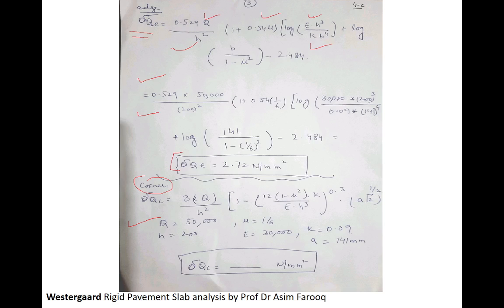I hope that you have learned today's session, and you also understand how we can determine the bedding modulus of different conditions when we have the bonded layer system and when we have the unbonded layer system, and also how we can determine the slab stresses at the corner, edge, as well as at the center of the slab.